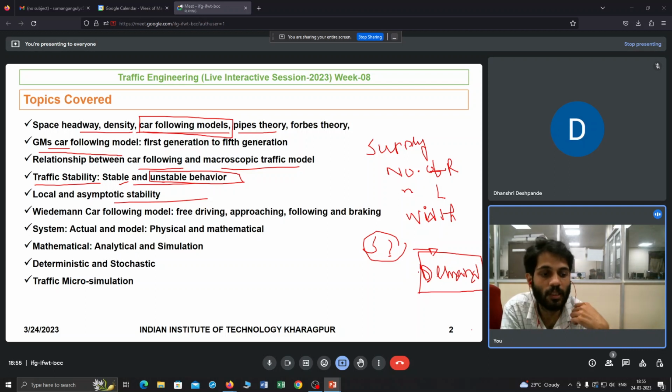And also what is the free flow speed in the morning based on the speed limit, what is the typical acceleration, right? So you want to know the typical or maximum acceleration, because otherwise it's a computer program. Maybe it is developed for some countries, so they have their default values. So now you have to replicate your field scenario, not their field scenario.